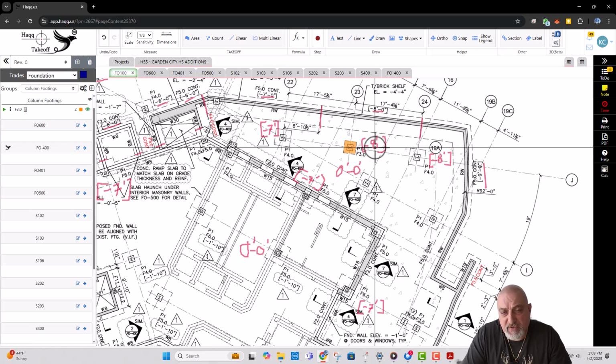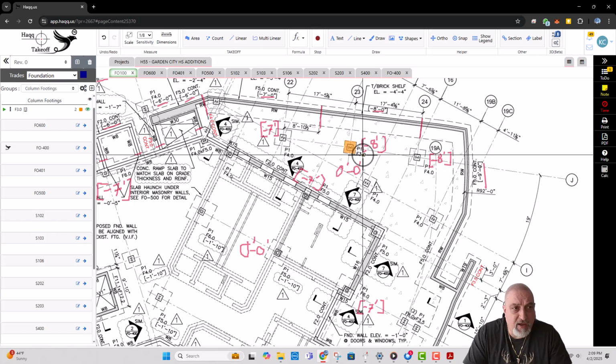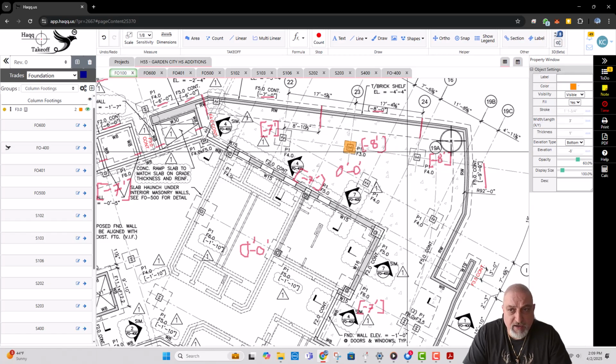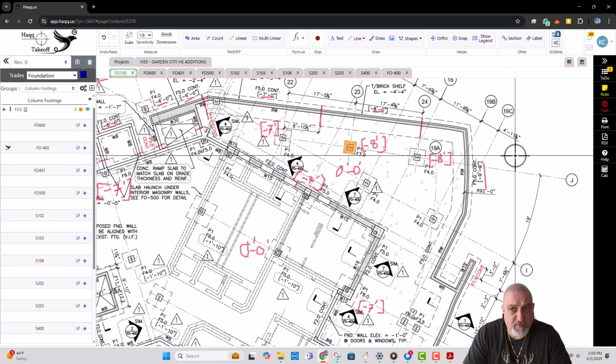This only affects the 3D view of the takeoff, and your 3D model will be in good shape. You will understand all the elevations. You can create another F3, but you don't have to. You just go here, click edit, and change the bottom of footing elevation.